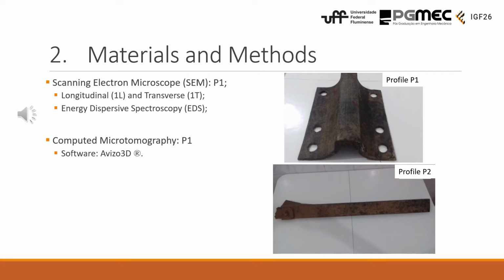We also used the energy dispersive spectroscopy to analyze the chemical compositions of those inclusions. And finally, we did a computed microtomography on samples from profile P1 to analyze the distribution of those inclusions inside the material and to quantify the volumetric fraction of those inclusions.